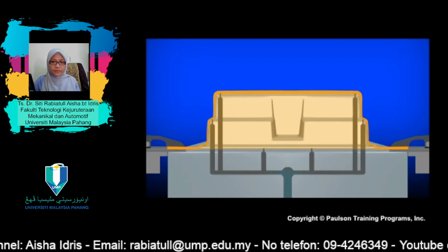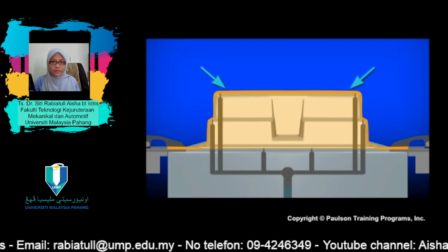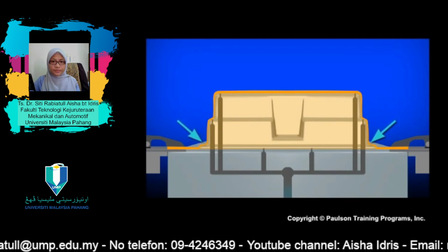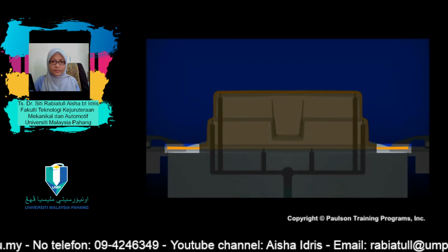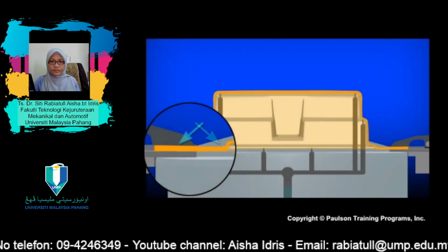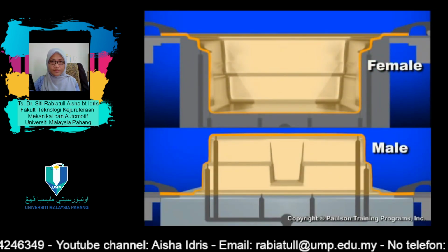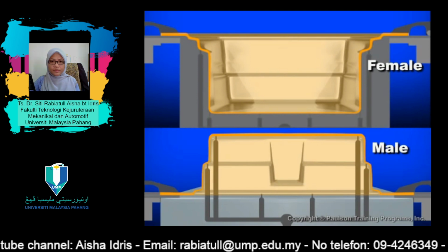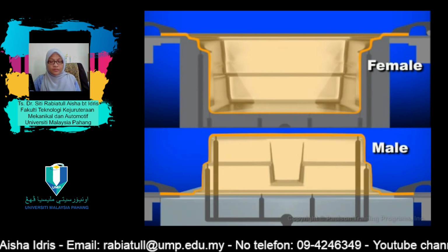The sheet distribution is the opposite of the previous mold, thick at the base of the formed part and a decreasing sidewall thickness towards the flange. The flange itself will have varying thickness, thin at the corners, thicker towards the clamp frame. The uneven thickness variation from both of these molds would usually be unsatisfactory. Methods to reduce plastic thickness variations will be described later.